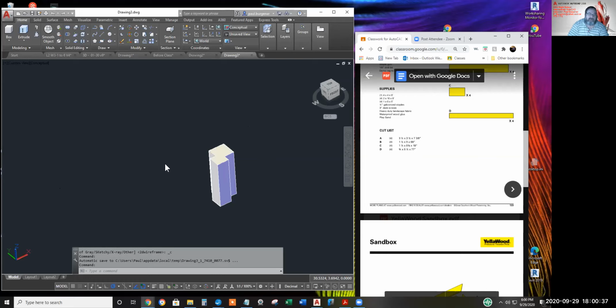Planning ahead, I believe the X will be the, what would I say, 68. Y for width will be 1.5. And the Z will be 9. So let's go box. Slit off of the box, pick a point, select length, rest my cursor perfectly in the X direction, and type, memory is so bad, these are 68, enter.